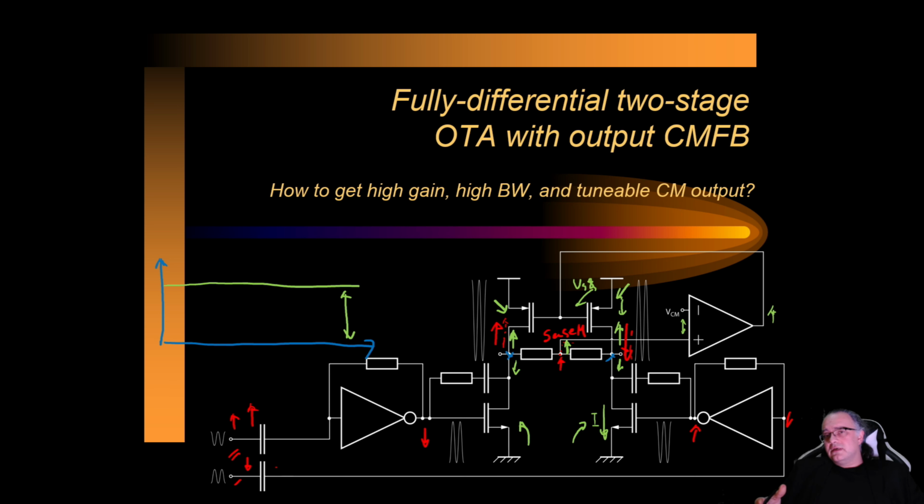And this means that as the pmos current reduces, the common mode needs to go downwards because the current is the same. So basically this will go to 0.4 volts. As I go to 0.4 volts here, then delta will eventually become 0, and then this node will not need to change anymore. It will be stabilized, setting a gate voltage which sets the source gate voltage that produces a certain current in the pmos transistor such that the common mode is at 0.4 volts, which I set. I can change this to 0.5, 0.6, and then the feedback will adjust the gate of the pmos transistors to the appropriate levels. So basically here I will get, for example, the common mode 0.4 volts, and on top of that I'll have my output.